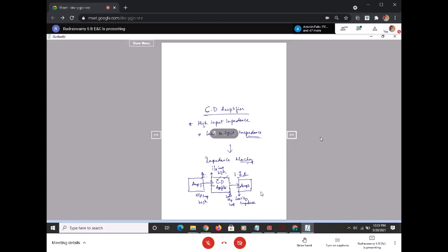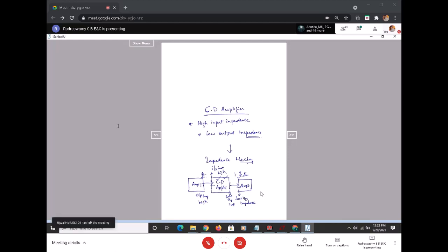So your common source amplifier is for amplification. The common drain is basically a source follower, where the output follows the input. That's it. Vout follows Vin with a gain of approximately 0.9 times. Not exact, I can never get one. Practically, if I design the common drain amplifier in the purest manner, I may go up to 0.95 or so, not beyond that.